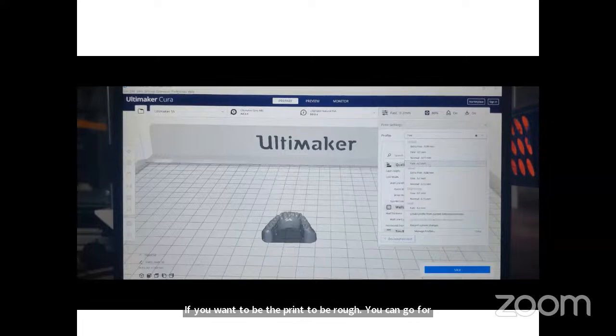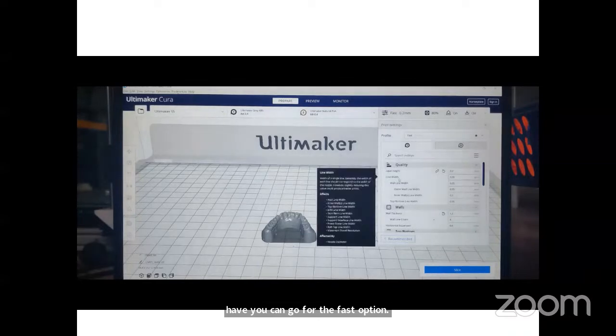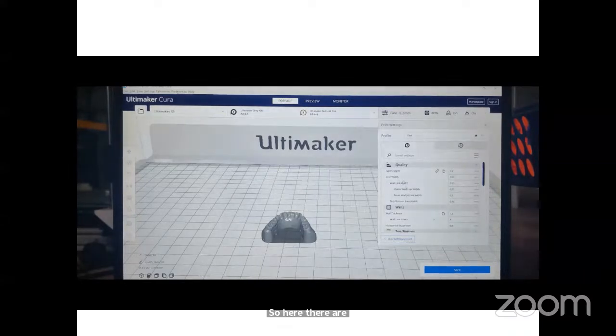If you go for fast, the print will be completed at a rapid rate. If you want to go for extra fine, the time will be increased, so for that you can go for 0.06 mm also. If you want it completed as soon as possible, then you can go for the fast option. Here there are other options that we can change as well.